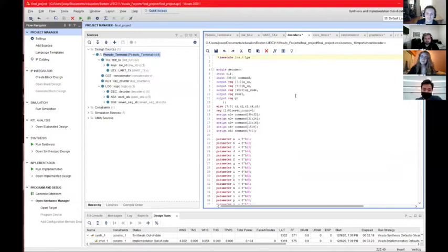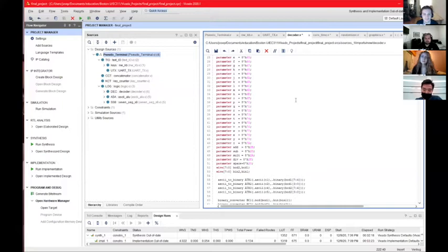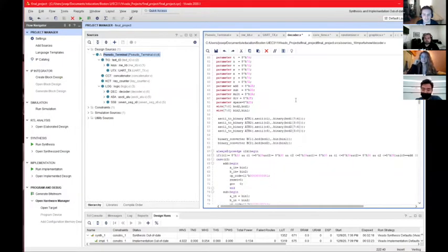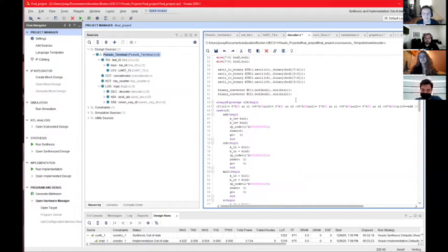received from the concatenator into the logic module. First, the 40 bits are partitioned into 5 equal length wires called C1 to C5. Since the ALU performs 2-digit operations, the middle bit must be a mathematical operator such as plus, minus, multiplication, X, or division. The first 2 partitions are also converted from ASCII to binary coded decimal, and then finally to binary values for use in the ALU.